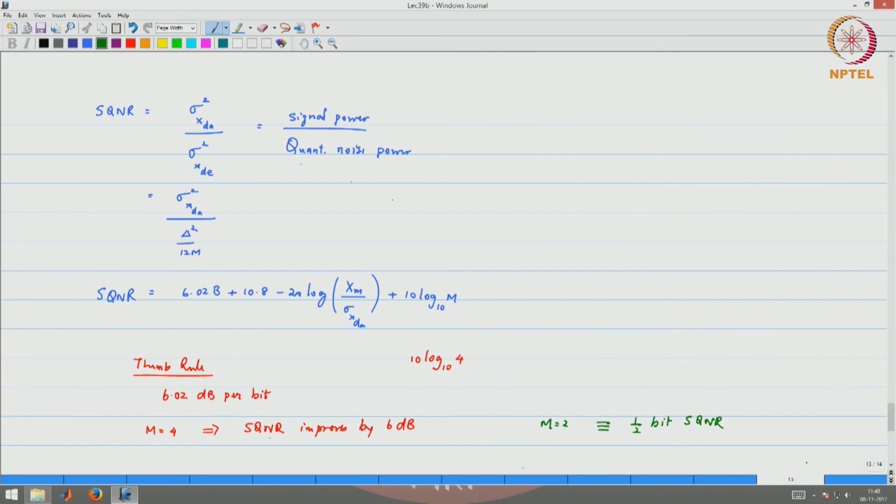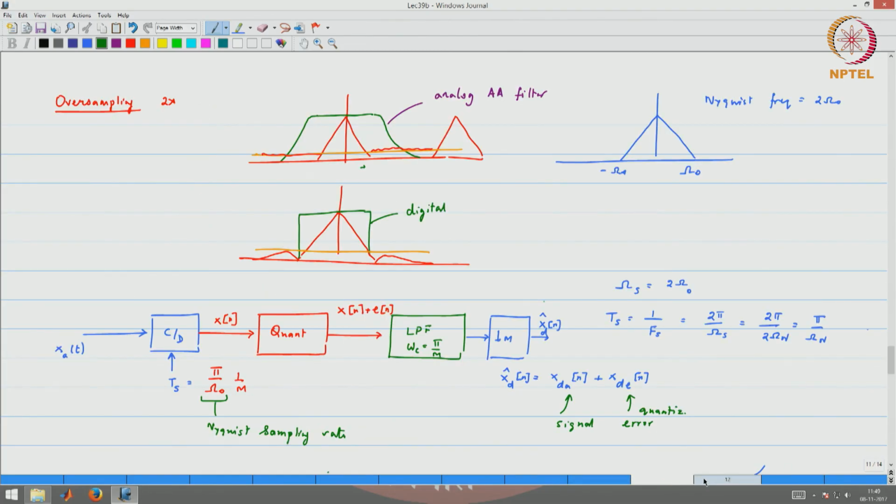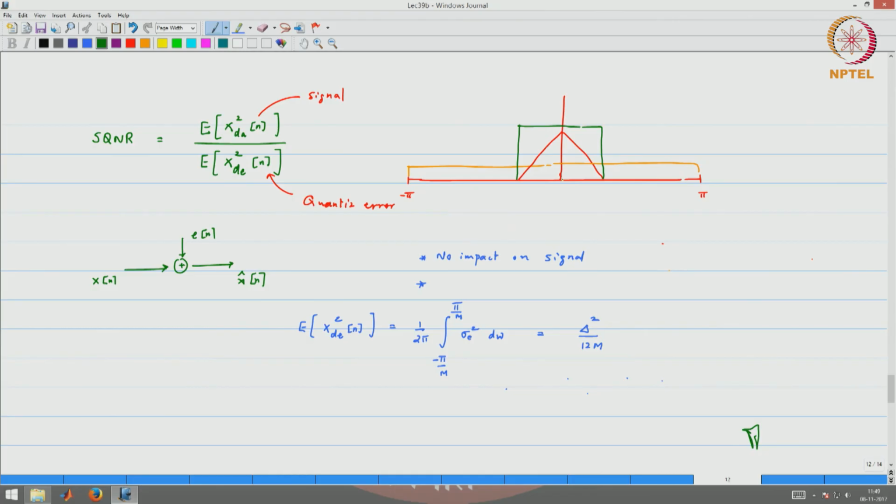This is good enough, we actually achieved it, but keep in mind that if you want to go from 8-bit precision, let us say you have an 8-bit quantizer, and you want to get 16 bits of equivalent performance, you will find that m will become very large. So, you will have to have a lot of complexity. Here is where the thought process comes in, and we look at this figure, and the question that arises: does the quantization error need to be spectrally flat?